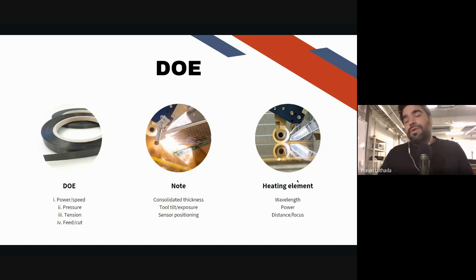You definitely want to know what temperature your material is reaching and that it's not degrading. So at DOE, you should definitely get a sense of this. And with that path, you are usually also able to trace it back. There's soon the capability to even have it recorded for the entire layup, so you are able to go back in the history. This is very critical for you to know that you have not degraded your thermoplastic layup.